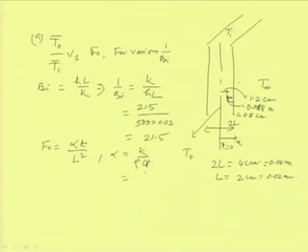The aluminum k value is again 215, rho is 2700 kg per meter cube, and for Cp we have to be very careful to check the dimensions, whether they are all in SI units, so that the things become dimensionless. This is a very important part.